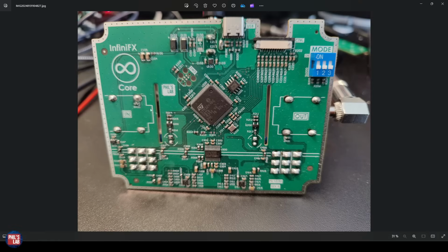So what I'm doing in my case, I'm actually now leaving for this measurement the input jack unplugged. And this is actually a switch jack. So if I leave the input jack unplugged, the input is grounded by the mechanical terminals of the jack itself. We are feeding our system through the front ends, codec, STM32H7, codec, front end, and then the output we are taking with this 1/4-inch jack that is feeding the input channel of the QA403.